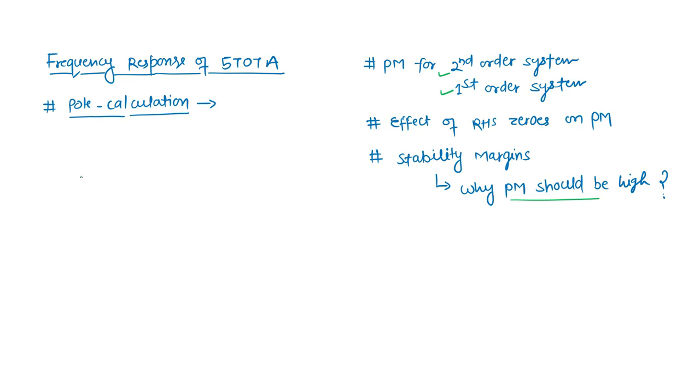Before that, I want to calculate the pole location. So what is the pole actually? So we have seen from the transfer function, this is my transfer function. What we have seen for pole, it should be infinite. So for that, my V out should be infinite for a particular given input, which we usually short for the calculation of pole. Okay, let's first take the simple example.